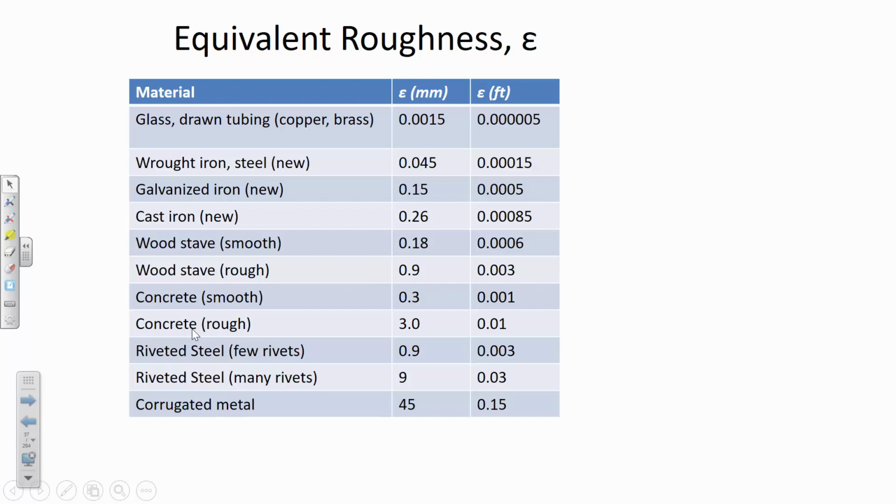But sometimes in sewer pipes that can be a problem, because in sewers there's a gas that's called hydrogen sulfide that's formed. It dissolves in the water and it forms sulfuric acid that can erode a concrete sewer pipe. And so sometimes if you're designing the flow conditions, assuming that you've got a really smooth, newly manufactured concrete, over time the material properties can change, and then if the pipe becomes more rough because the cement is being dissolved out, then that would mean it's less efficient for carrying flow. So it's kind of a compounding problem.